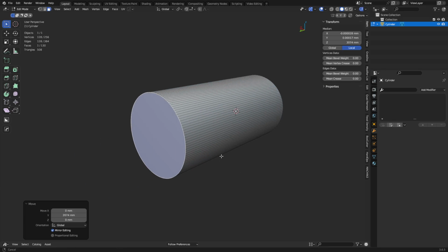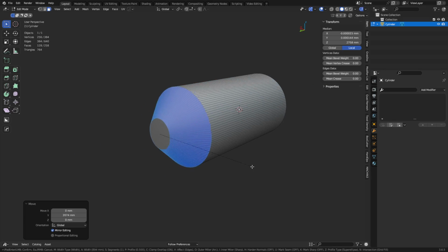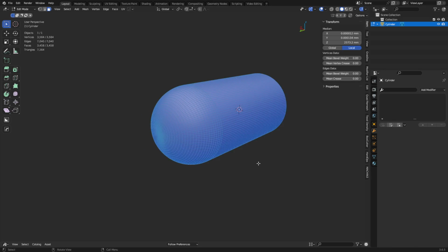If we were to take this piece here and we did a bevel on it, hit C to clamp. You can mouse wheel up. You can do this number. Okay, hit A, M, merge by distance. You'll have doubles. All right, now Quad Remesher.